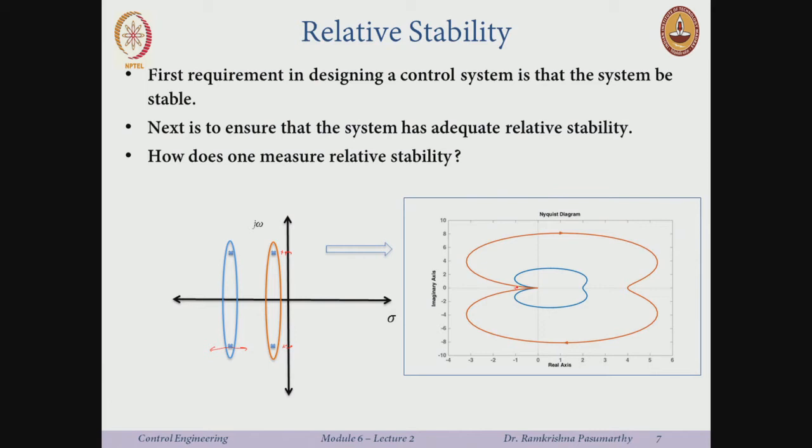So, what is the point of interest, right? As long as P equal to 0, say the open loop system is stable, I just want Z to be 0, right. And if Z is 0, Nyquist tells me that the system is stable. Now, who decides this? So, this is my guard, right, who says, well, you cross this line, you trespass and you become unstable. So, the idea would be, well, I will just stay as far as possible from this number, -1 plus j0.